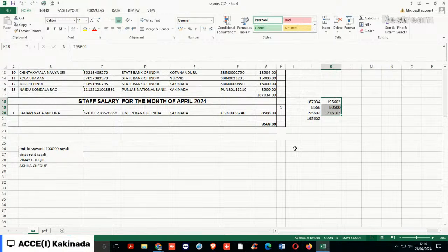Here, one of the construction mistakes that takes place is a gap that we see in the lateral ties. This gap should not be left after fabrication. Why? Because, as we just saw, the main bars buckle under the increased axial loads from the seismic effect. With this lack of lateral confinement from the lateral tie, the bars simply buckle in the lateral direction, as there is no effective lateral restraint from the stirrup. This type of gap should not be there after placing the stirrup. That is also important when seismic resistant design is considered. Also, it is preferable to have a closer spacing of the ties compared to a larger tie spacing. That is also one of the requirements we have.